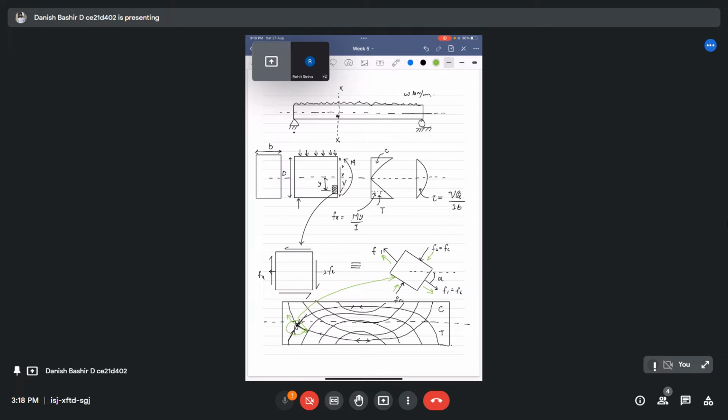Concrete is very good in compression, so I have not to do anything with that. But take these tensile forces that act on our small element. These tensile forces will try to create a crack like this. The crack will be like this. It is stretching it like this. It will try to get rupture like this from the middle one.